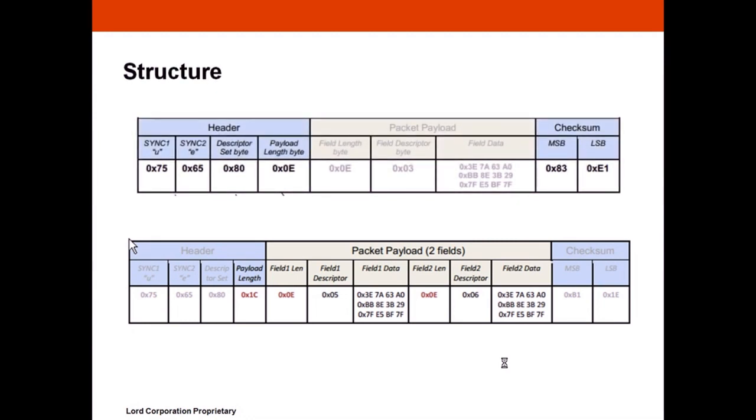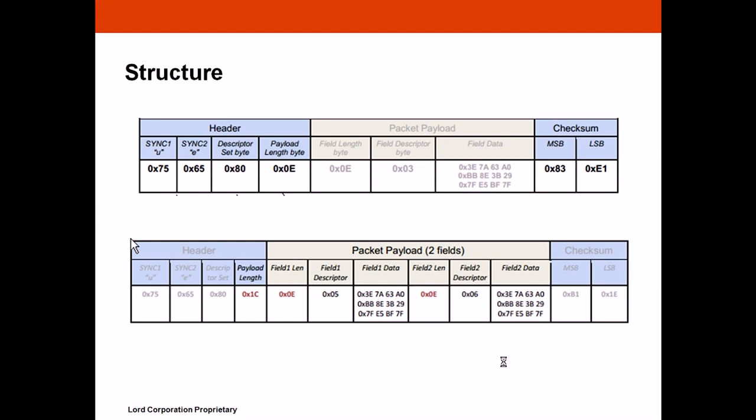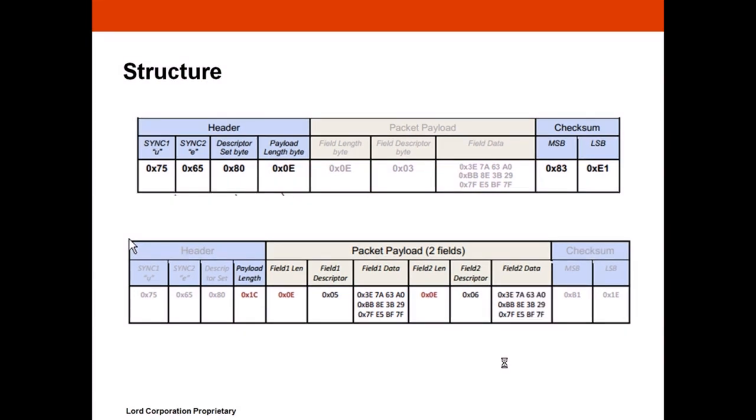So the structure of the packet is straightforward. If you've used packets before, it's very familiar. You may wonder why we designed another packet, but I'll show you as we go along why we needed to do that. The first 2 bytes are the start of packet. They're hex 7565. They translate into a lowercase u, lowercase e, making it easy to spot the packet if you're looking at a binary stream. It also has 5s in both values, which allow autobauding to pick up on a baud rate.